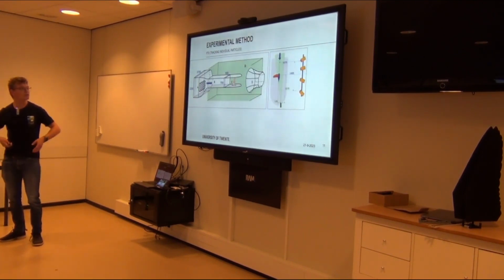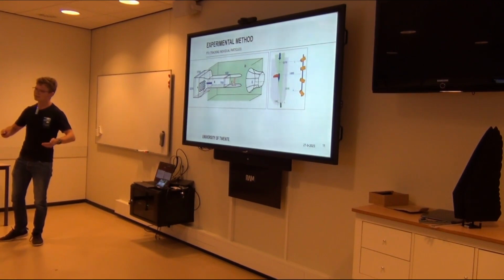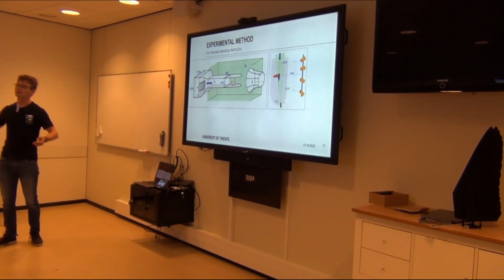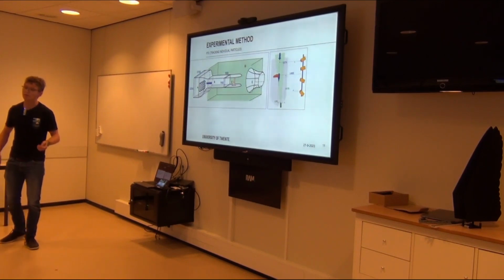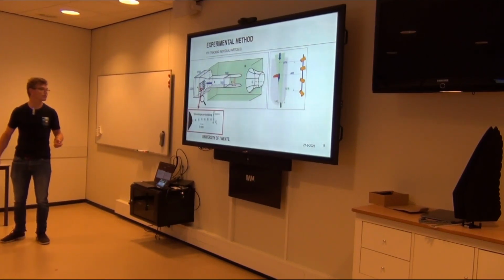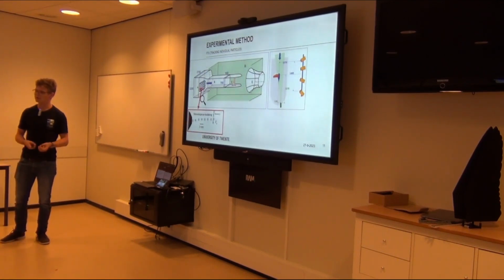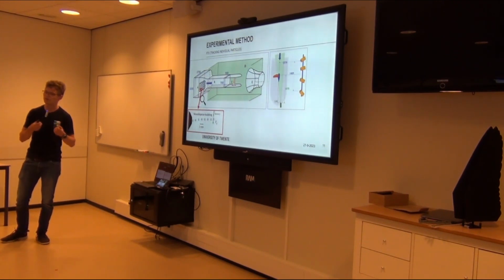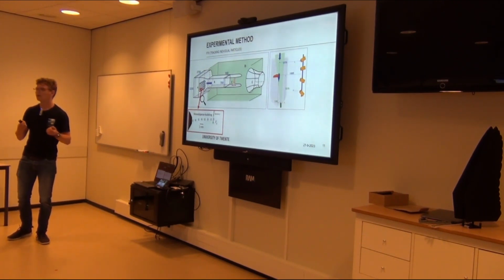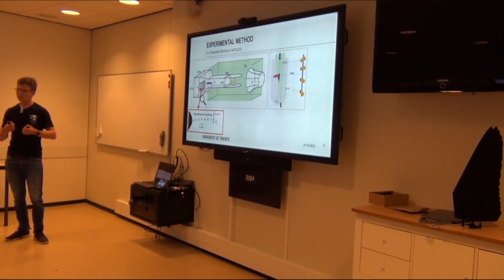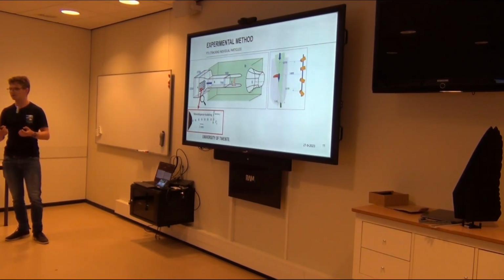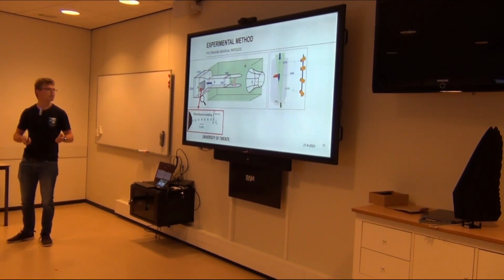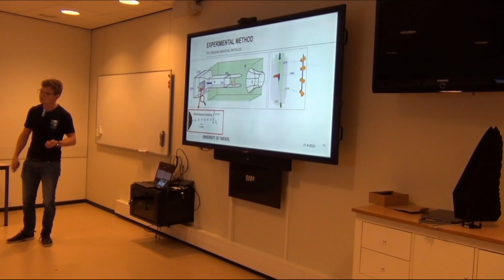Moving on, when we ramped up complexity a little bit, we had to start adapting our experimental setup. Like Stefano already said, we had to move to new tracer particles. PIV tracers are very small, 1 micrometer. To be able to do measurements on a larger volume, we needed better particles, particles that reflected more light. And for this we turned to helium-filled soap bubbles.